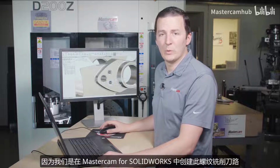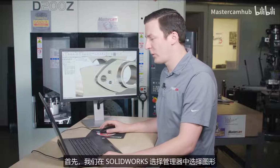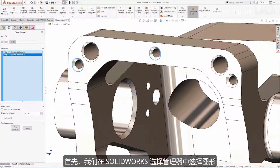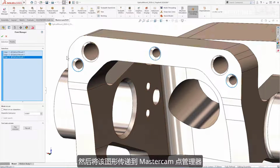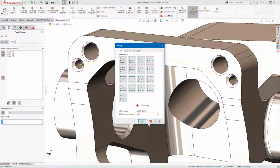Because we're creating this thread mill toolpath in Mastercam for SolidWorks, selection is a 2-part process. First, we select the geometry in the SolidWorks Selection Manager, and that geometry is passed to the Mastercam Point Manager, where we can sort the order that the holes are thread milled in.